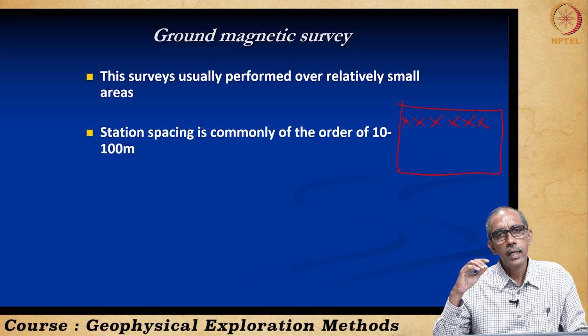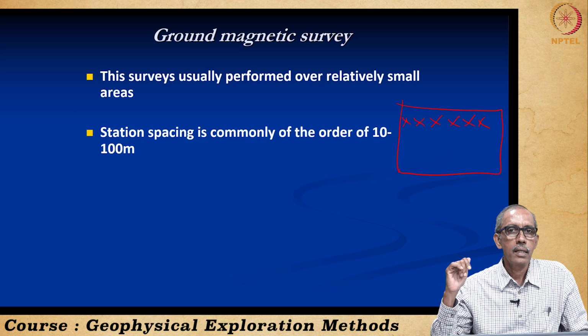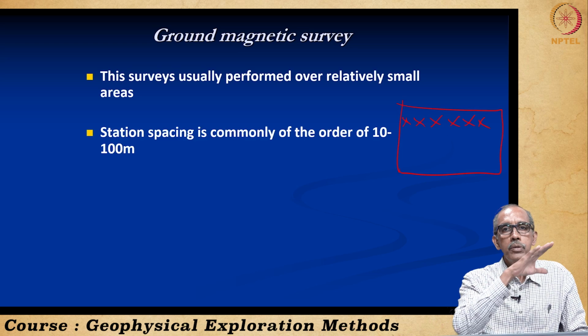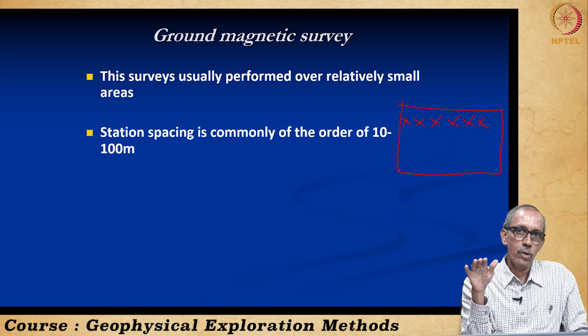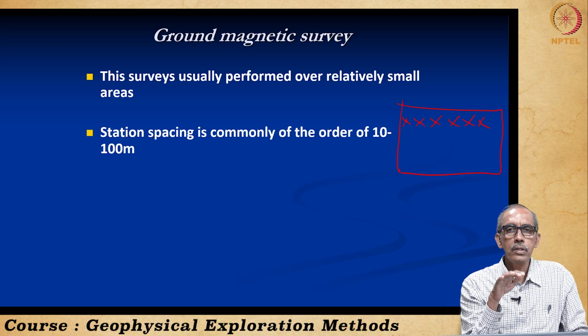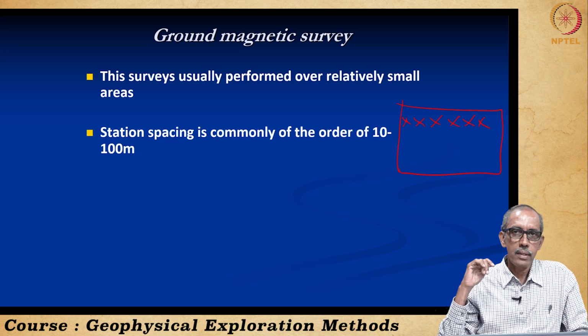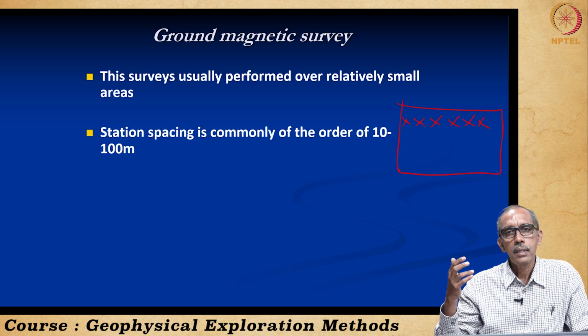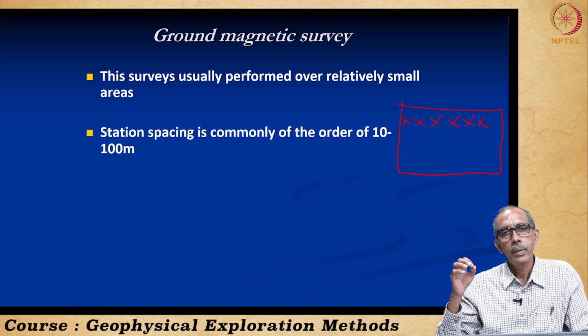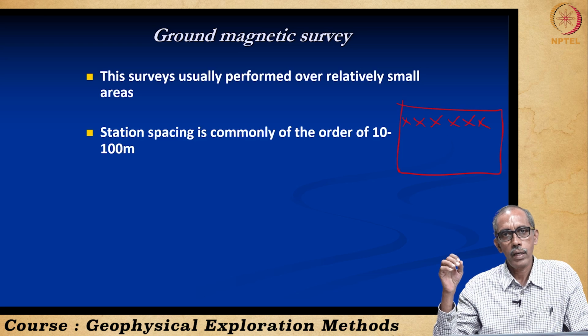Are you looking for buried artifacts? Are you looking for a buried steel drum? The size may be very small. Or you are trying to understand how the depth to the basement rock varies over the surface of the earth, or are you searching for a thick sedimentary basin? Obviously, our resolution of survey, not only in this method but in all the other geophysical methods also, the distance at which we want to collect information depends on the aim of our survey.